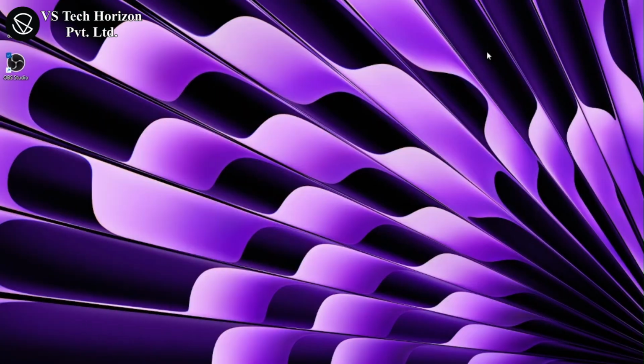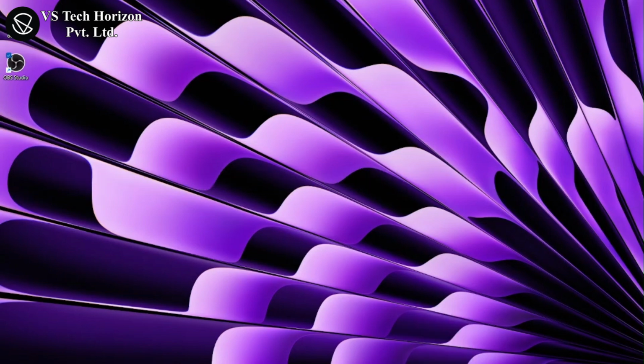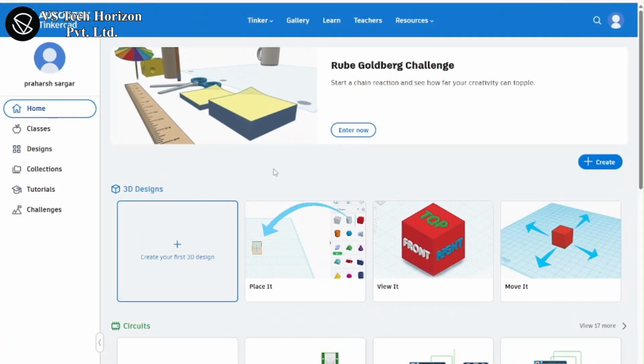Hello everyone. Today we will be learning how to make an automatic room light using Arduino Uno in Tinkercad. So let's get started. First you'll need to open Chrome and open the Tinkercad website. Once the website is opened, you will need to click on the Create button and click on Circuits.